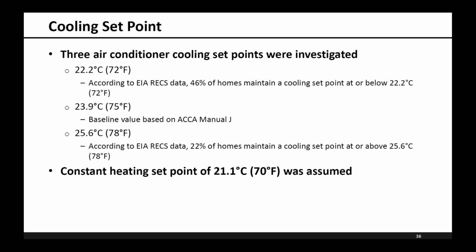The issue we had with that is that the cooling set point is not just an occupant preference, because people can adjust the set point in order to improve comfort. So if there's high humidity inside, a homeowner may reduce their cooling set point to try and make the house more comfortable. So we didn't feel it was going to be realistic to incorporate the cooling set point in with the rest of the things we looked at for occupant behavior.